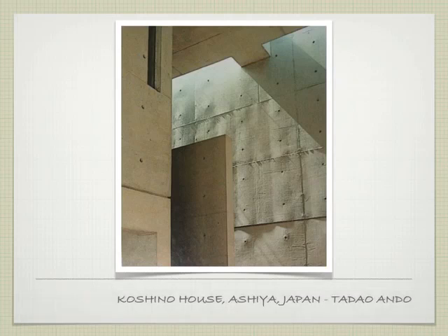So what Tadao Ando did on this particular house is he reduced the number of form ties that were used to hold the sheet of plywood in place. Usually it's at least 8 on a sheet of plywood. He reduced it to 6. When he did that on the formwork, it allowed the formwork to billow just slightly. So when you put the concrete inside, the formwork pillows out just a little bit in between each one of these. And so that little bit of flex gives a little bit of extra texture to the concrete wall itself. And in this particular example, this was designed as an exposed concrete wall. So he was thinking about how the building was going to be made and using that to his own advantage in how he's exposing the wall.